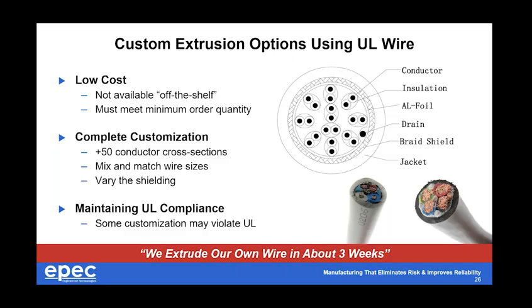If you need 20 twisted pairs all within one bundle, UL will comply with that, or we can make that using the existing UL process we have, as long as we can print the UL marking on the wire jacket, as long as we're using PVC that can survive either 80 degrees C or 105 degrees C, and then we can certify that this cable will survive the 300 volt or 600 volt requirement as noted.